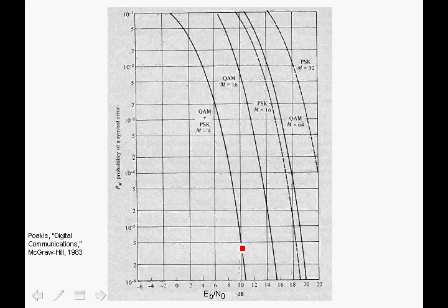So we can actually change rates depending on signal-to-noise ratio. And in advanced modulation schemes, this is called rate scaling. By adding intelligence to the communication link, the actual link can adapt to the different signal-to-noise ratio scenarios in which the transmitter and receiver are closer or further away. Then we can adjust the rates accordingly. So again, note that when we have a low signal-to-noise ratio, we can only support, for example, QPSK, and we cannot support, for example, 16 QAM because we'd have a very large symbol error rate.